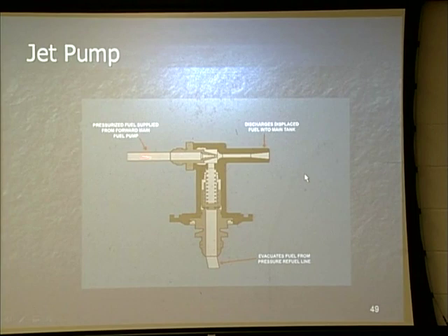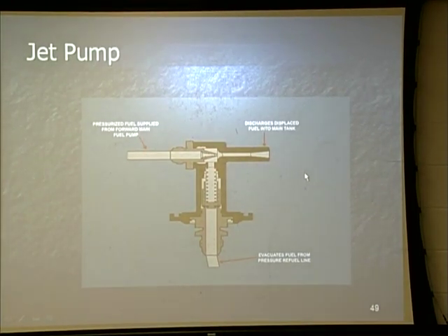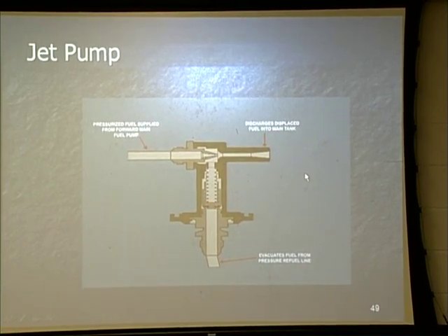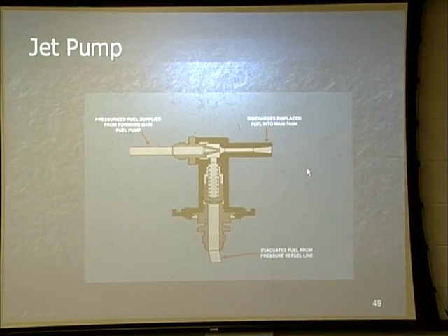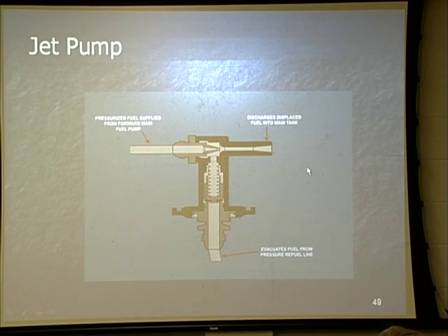And in closing it now, although that pressure fuel is still going through there, it hasn't stopped. Because there's no weight, that air pressure is non-existent. That spring is keeping that door closed, so it's not doing anything. It's just circulating. I see what you're saying, that fuel's still going into the main tank. Yes. It's going back into the main tank. Yes, sir. And there's one on the left and there's one on the right.